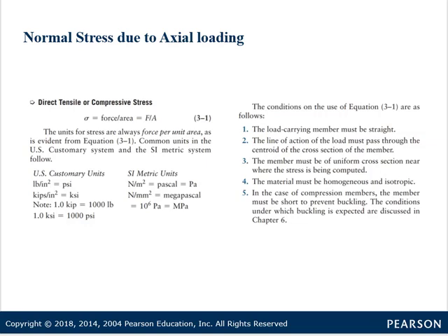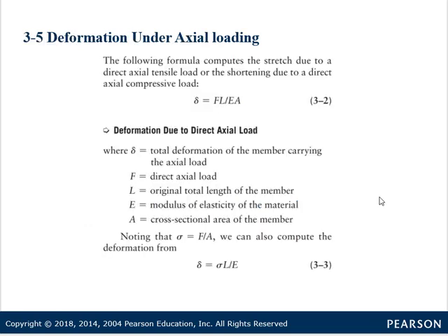Now, if we're talking about deformation under those stresses, I'm going to offer this equation here. It's equation 3.2, where the deformation equals the force times the length divided by E, which is the modulus of elasticity, divided by A, which is the cross-section.